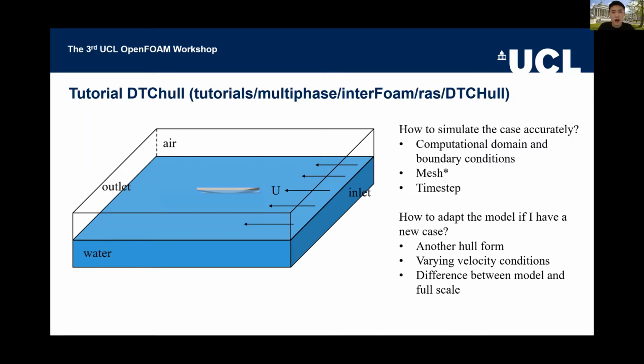So a very common way to simulate this flow problem is to fix the geometry. We fix the ship inside the domain, but we make the water flow. So the water and the ship have a relative velocity, which is U here, and in real life it's the same as having U equal to 0 but making the ship advance. In this treatment, the hull is always inside the water and we solve the fluid mesh, so the mesh will not be destroyed by the ship motion.